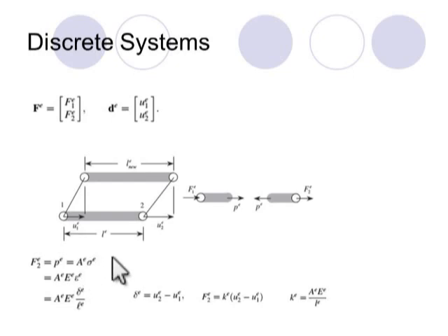Now let's write the forces for each node. F2 is equal to the normal force. Here it is area multiplied by the stress, and from Hooke's law we know that it is area multiplied by E, the Young modulus, multiplied by the strain, and the strain is equal to delta divided by L. Now delta, the amount of elongation, is the difference between the displacements, right? Simple. It is U2e minus U1e.